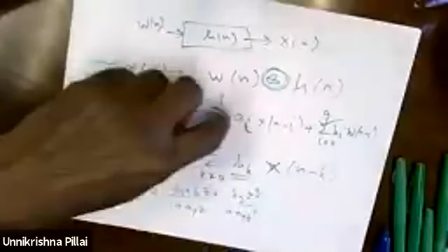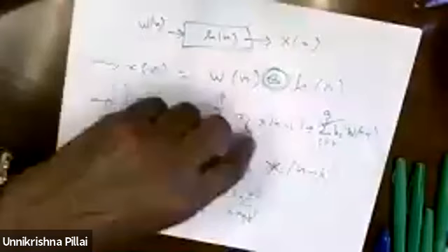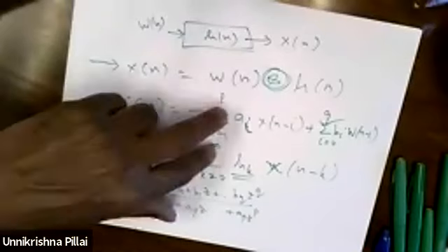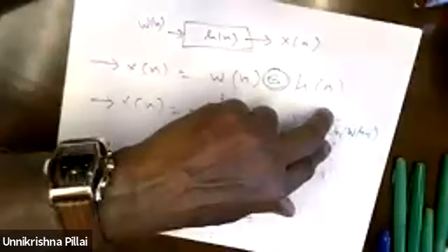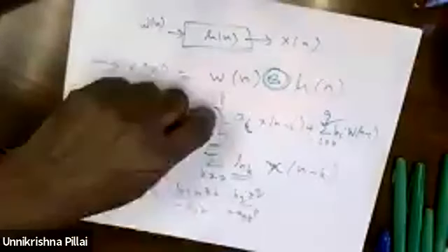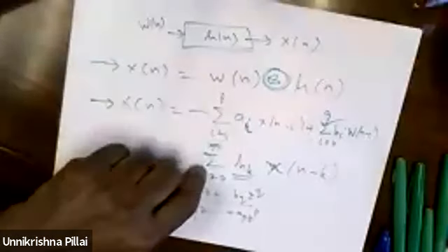So two ways to look at this. If you write it as a convolution, it will be an infinite convolution. But you can also write it in terms of regression into the past, into the recent past. Then you are only using P samples here, Q samples here. Here you are using all the samples from the past. Pick which one you choose.